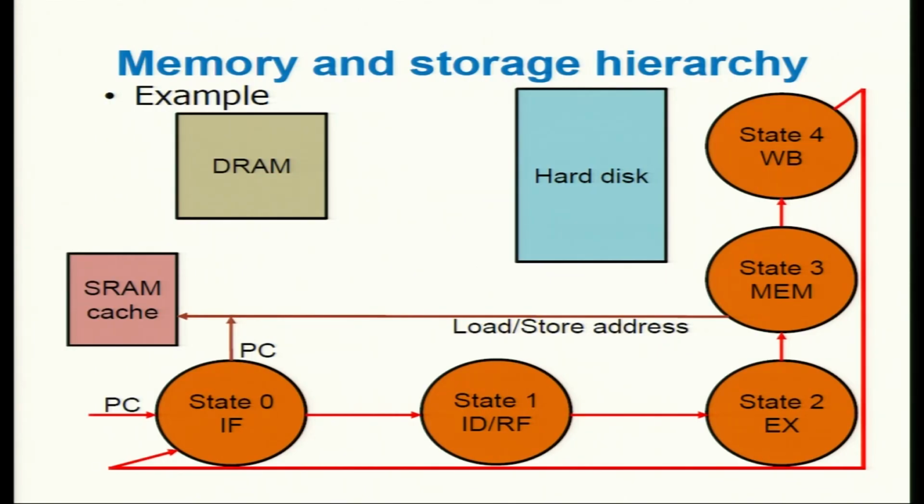So what will happen when we access that? Well, let's assume that the number of accesses is n. Only a fraction of that will come back, because typically the cache won't be able to deliver everything. So let's say a fraction x is found in the SRAM and returned to the processor, and that takes time t1. The remaining fraction will go to DRAM, that is n times (1 minus x), because they were not found in this particular cache.